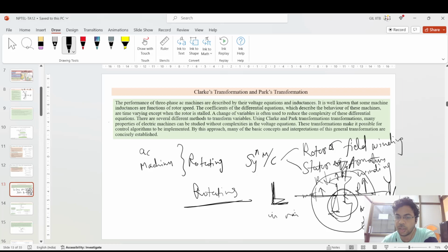So actually the main crux is that the L is variable. Why variable? Because the reluctance is variable. In this situation, you have to write multiple equations when it is rotating. Suppose your rotor comes to this position, then you have to write a different equation.